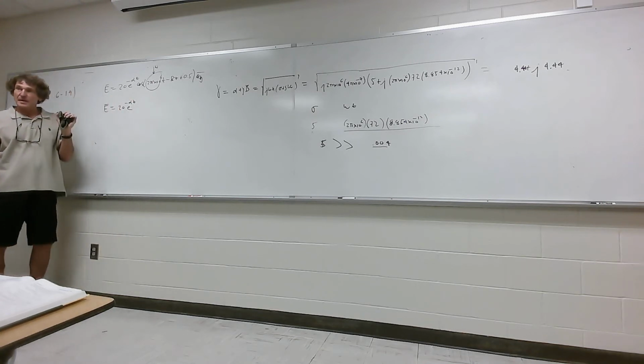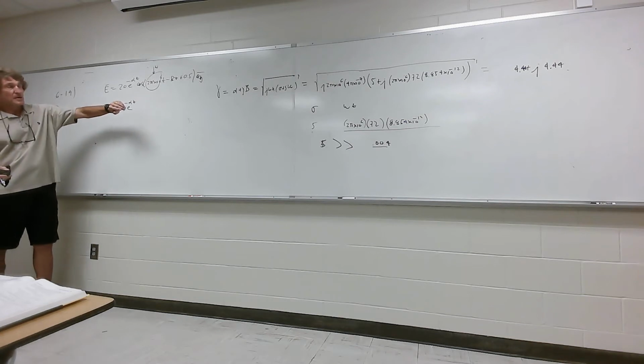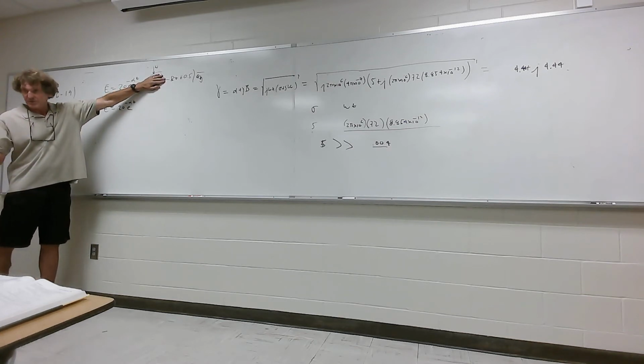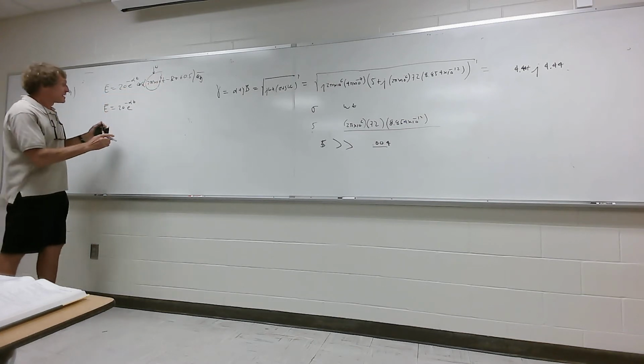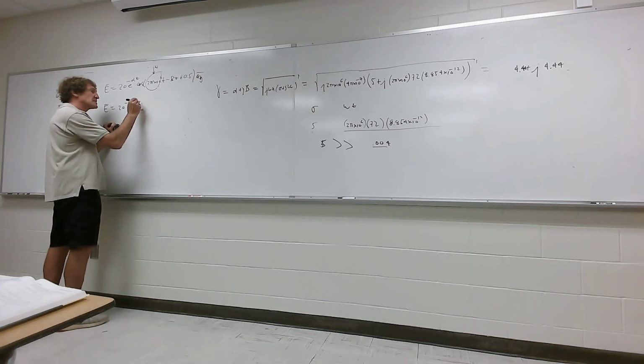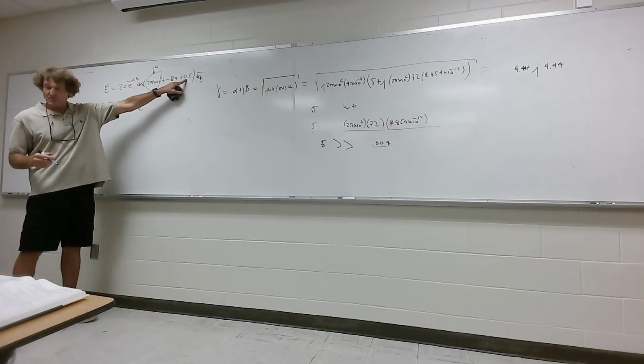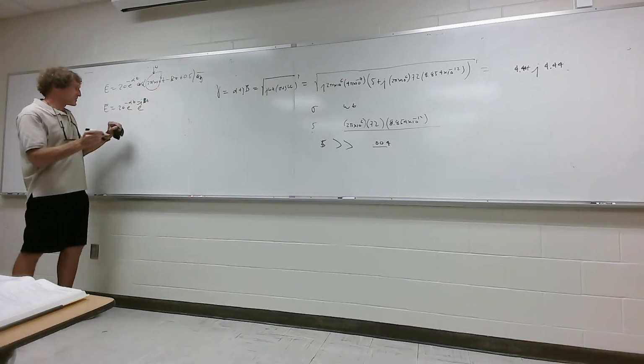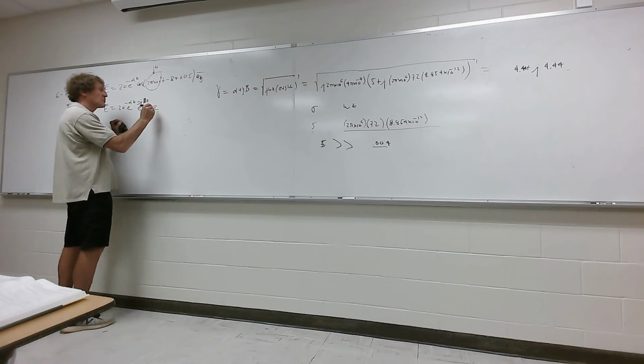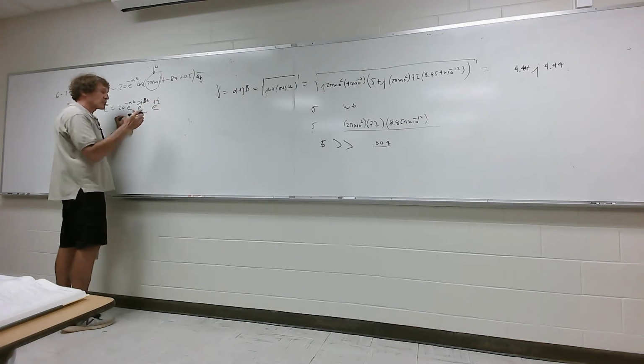That's not a problem. Now, when I go to the phasor form, that omega vanishes, right? And what happens? Then I get e to the minus j beta z. I know beta's 4.44. And this is in radians, right? So then I have to say it's e to the what? That's going to be j 1/2 or 0.5.